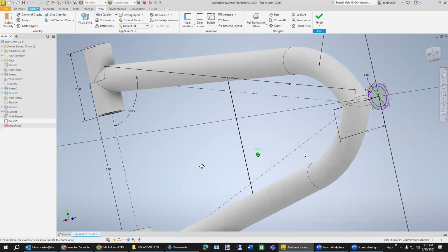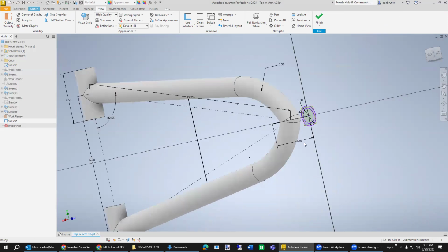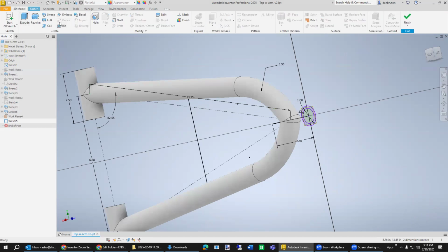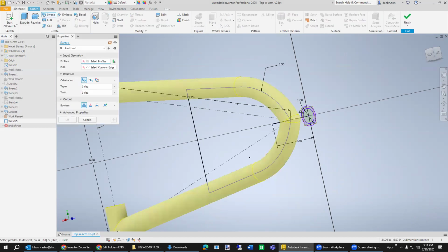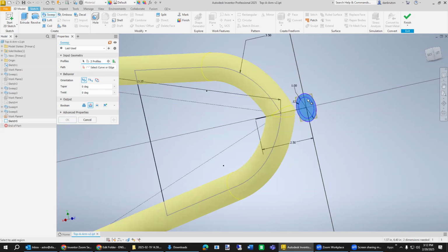That's all right. Let's go ahead and perform our sweep. Now we are going to have to do a cut because we got to notch this out to represent what the machine shop lathe does. So we will begin our sweep like this, and then we will go over to, okay, and for this first part, I need to make sure it's a cut, and I need to select the profile, which is the outermost, so it does everything. So it's basically a solid circle when I use the outermost. And then go here, and then here, make sure that's a cut, just double check.